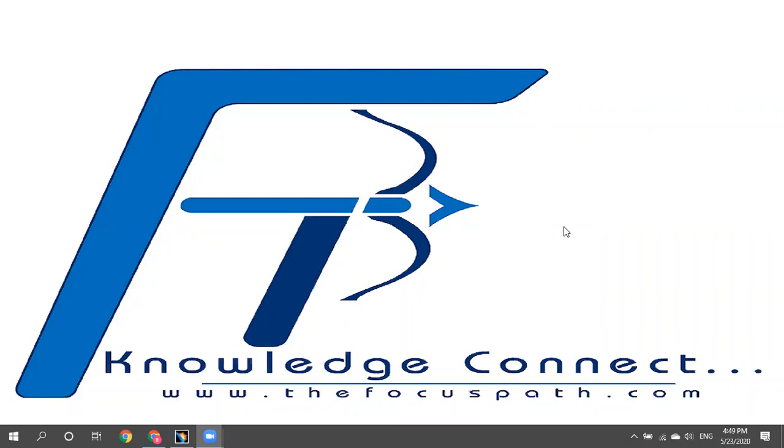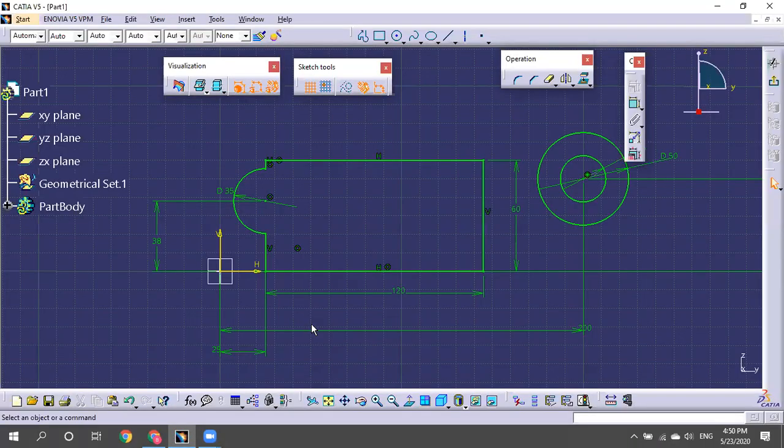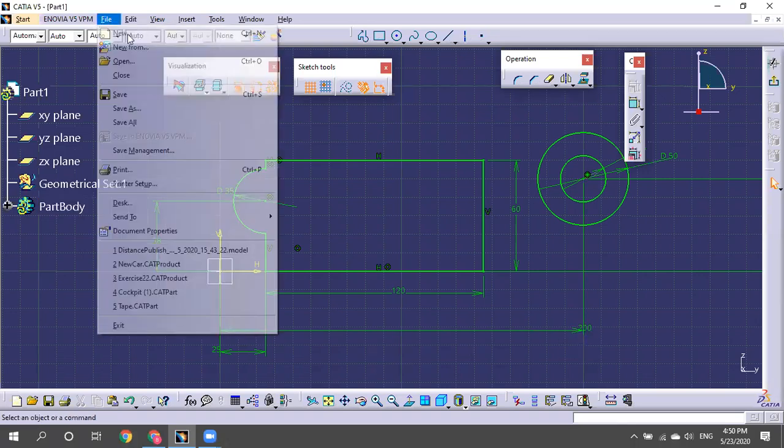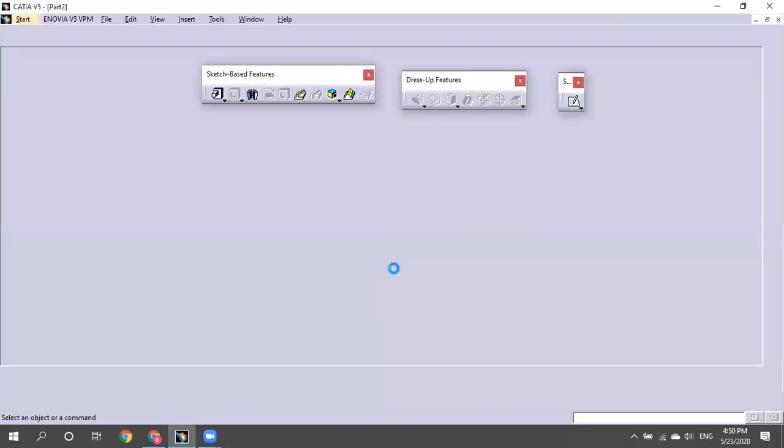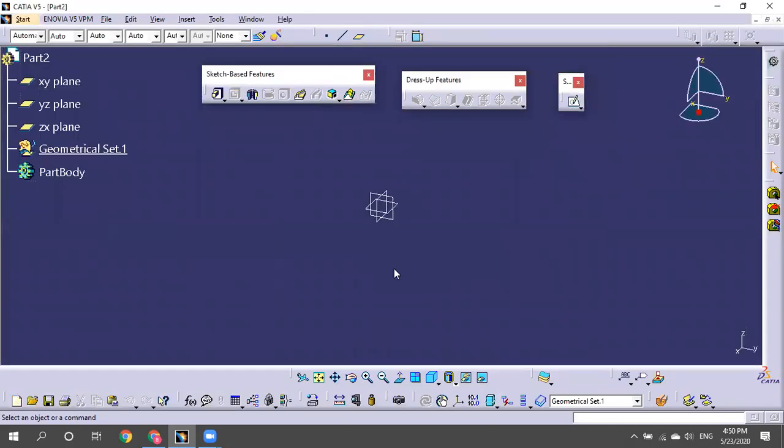After that, what you need to do is go to CATIA. You might have read the drawing, and from it, the vertical dimension of 200 is the maximum distance, so you start fixing that one. I'll open File, New, Part, and give a simple idea of how to start designing. So you get this screen. You might have read your drawing and decided that you have to draw a rectangle with coordinates of 200 mm horizontally and 300 mm vertically.